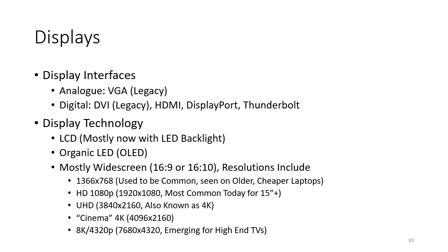The benefit for industrial application of DisplayPort is that the technology includes latching on the connector. So with HDMI, under shock and vibration, the actual HDMI cable could fall out, but with DisplayPort, it can be latched so that you've got more protection against shock and vibration. And these days we also see Thunderbolt, which is a combination of DisplayPort over USB-C, and that means that we can use a smaller connector but still get all the benefits of DisplayPort and also have other communications going on with USB at the same time.